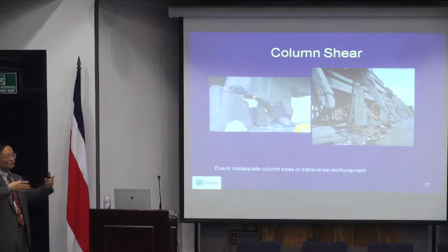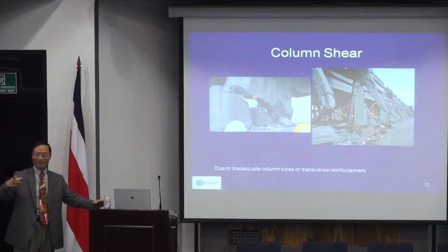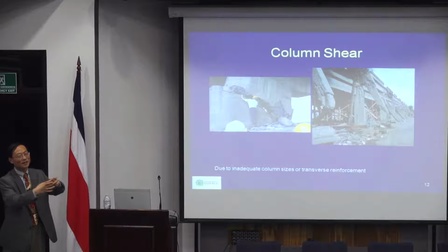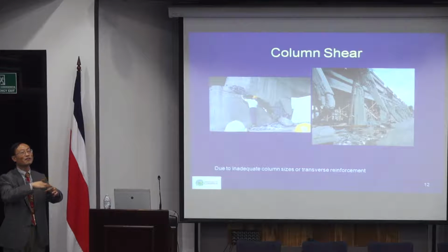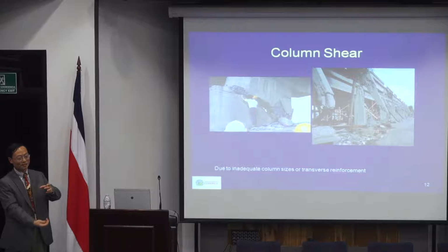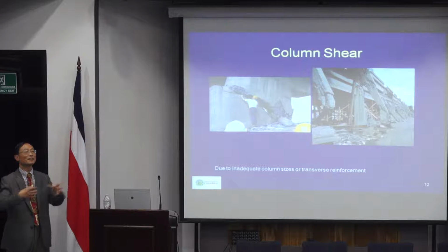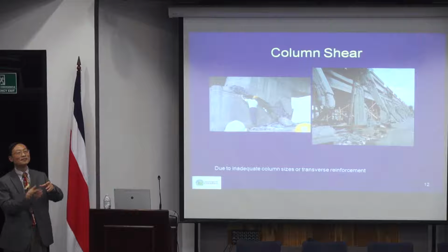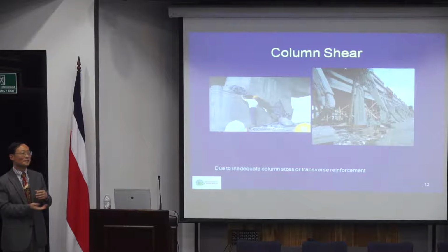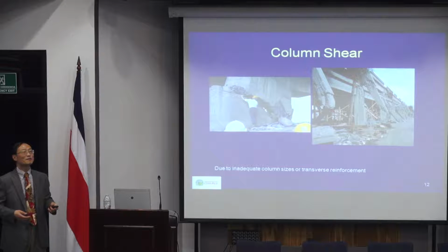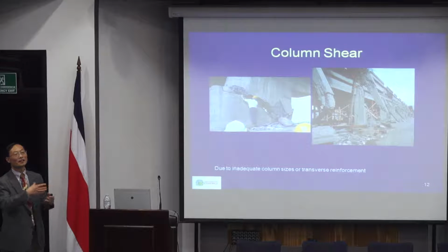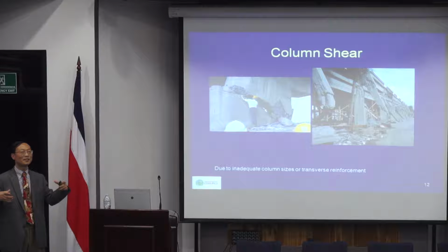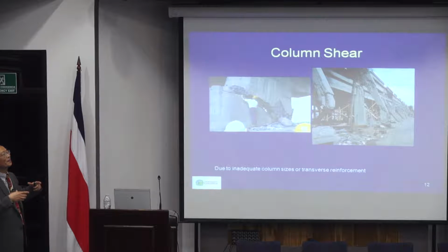Originally you basically just provide two pieces of steel plate. You put the steel plates together, and there's a little bit of space. You grout the space in, and you weld the two vertical lines. You provide confinement. Once you provide confinement, the steel tube itself is a shear reinforcement, so that will be able to carry sufficient shear. And now, because FRP has become cheaper and simpler, typically people are using FRP to wrap them up to provide shear reinforcement. That also provides confinement to increase ductility and to reduce earthquake load.